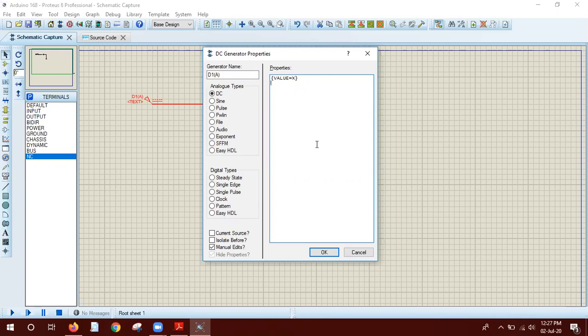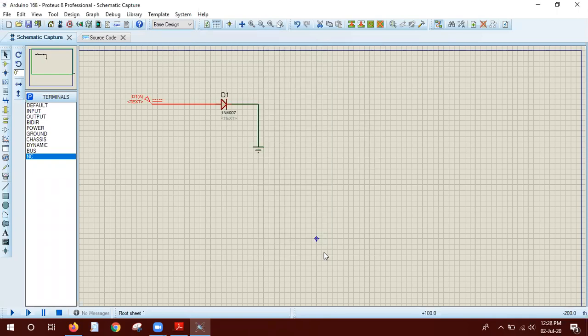It will vary the voltage from 0 to a certain level, and that will help our graph understanding. And what else do we need? The IV characteristics curve. That means we need the diode current, isn't it? We give voltage, and we need to see the current.